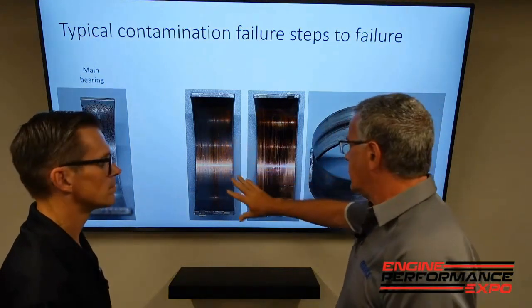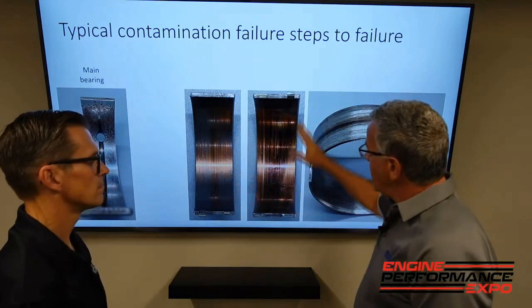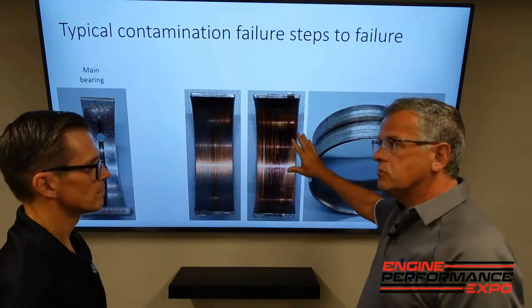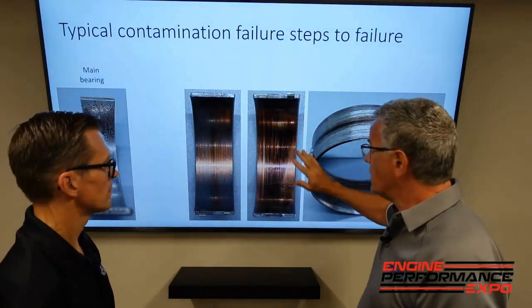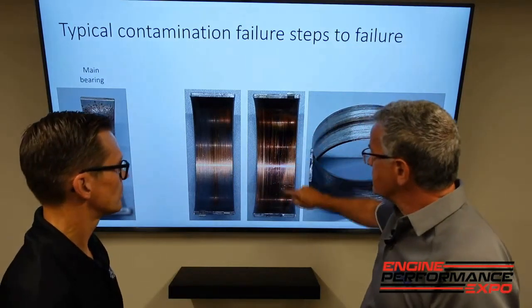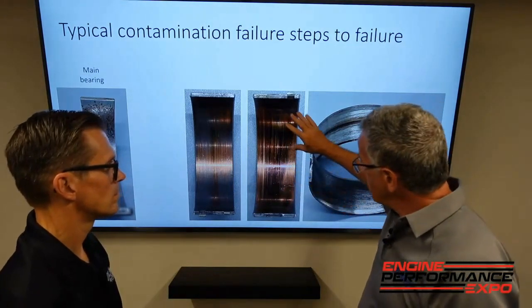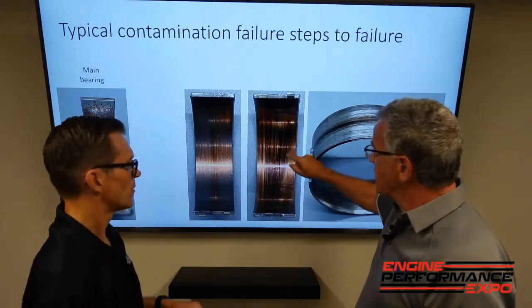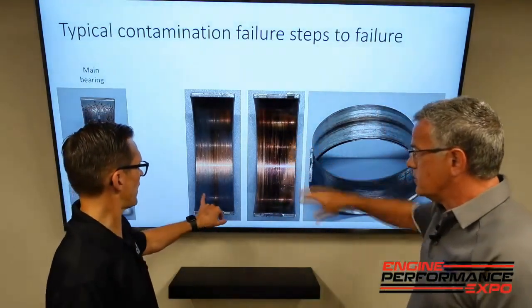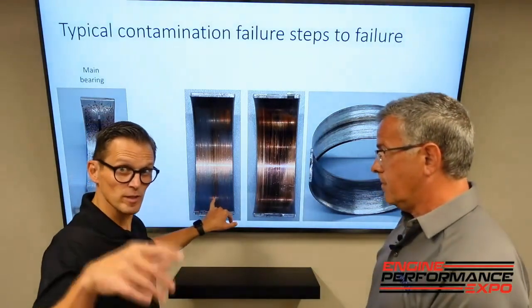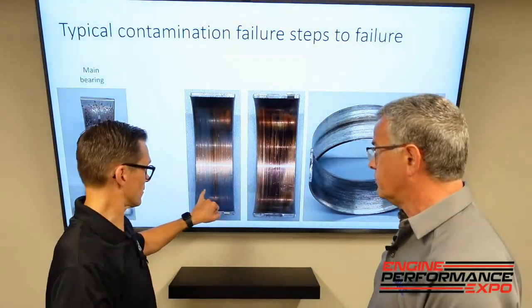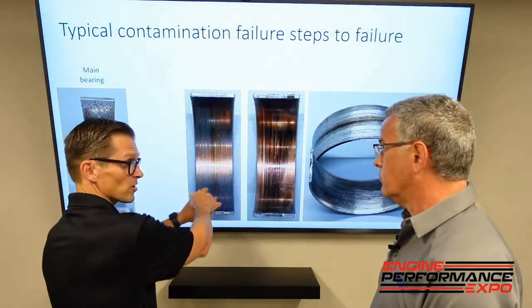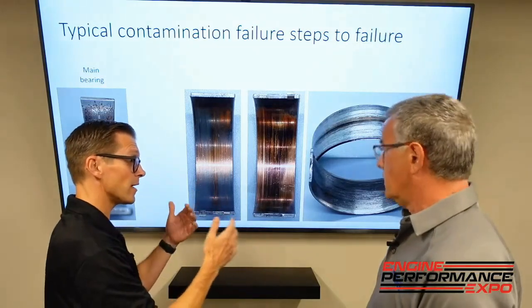That's pretty bad. Now we go to the next bearing, and there is no gray. There's no overlay at all. It's gone. You're getting a lot of surface temperature because of losing oil. Clearance got bigger, and you're actually getting burnt oil embedded in. Now that overlay, just for future reference because we're going to talk about it later, the material is tin and lead, correct?